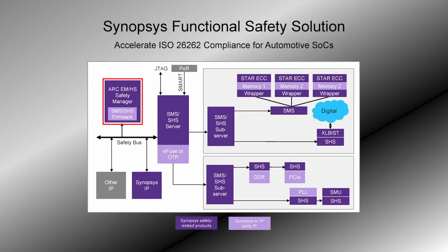This diagram shows the Safety Manager, which in this instance is a Synopsys ARC processor, connected to the top-level server via the Safety Bus. On power-up, you can invoke the Smart Mode to run a predefined set of test and repair sequences using the SMS server. The server then hands control over to the Safety Manager. The Safety Manager processor allows the user to create POST and mission mode tests via firmware.